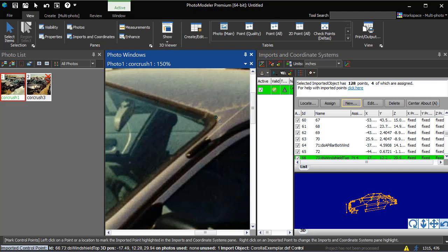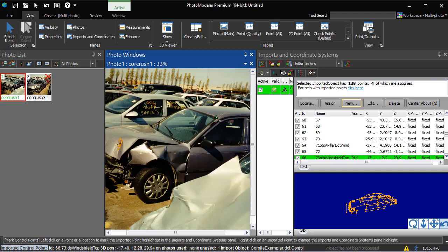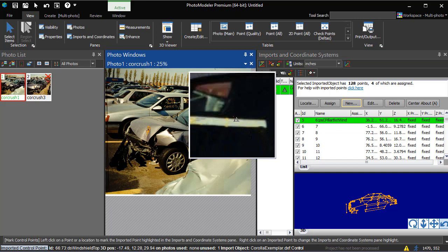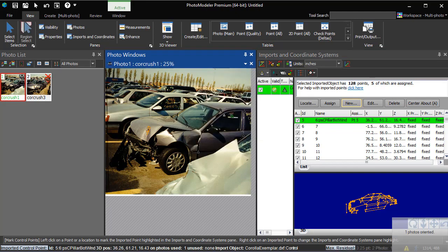All our points so far are covering this one plane of the driver's side. This point, passenger side C-pillar bottom window, represents a point on the other side of the car. This can be viewed through the windows. We now have some depth coverage in the photo. Enough points have been marked for the project to process. The camera's position and inverse camera focal length have been solved. This processing has been done using the minimum number of points.